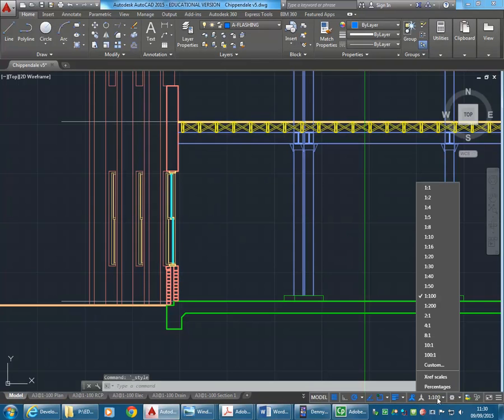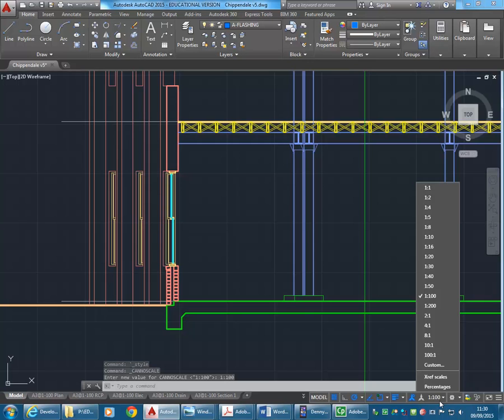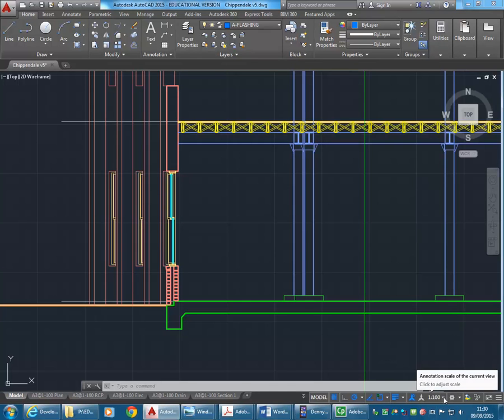So that means you need to know the scale here and set it in that annotative scale option. Every time you use annotative text, it uses whatever scale is set there. So you don't need to choose it every time, you can just leave it on the one you are using. You select your note style, and you change your scale here. Will it update the scale of the annotated text as well? Only the new ones. You don't want it to change the old ones.